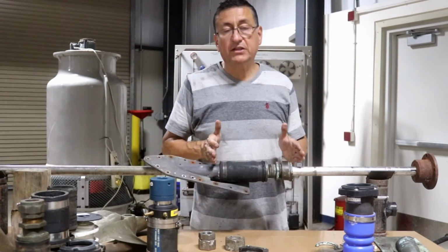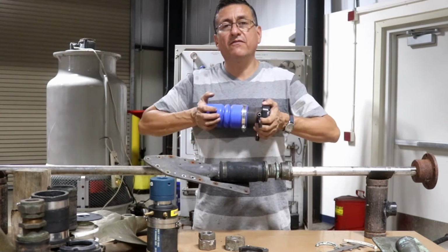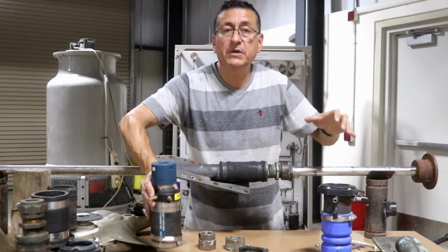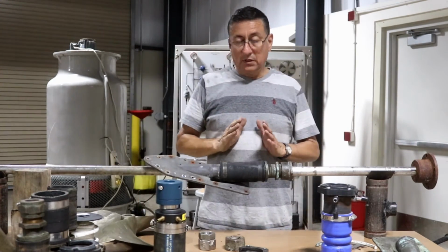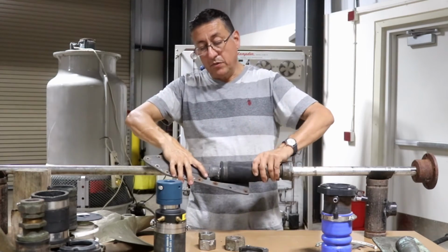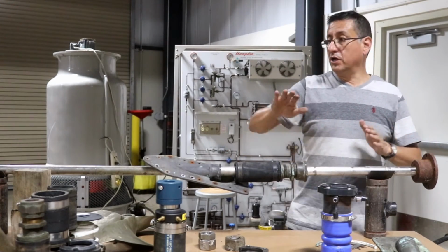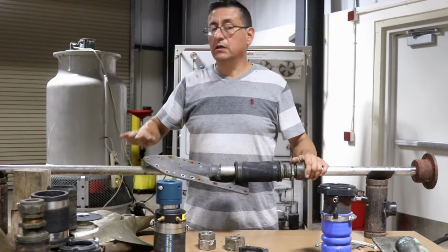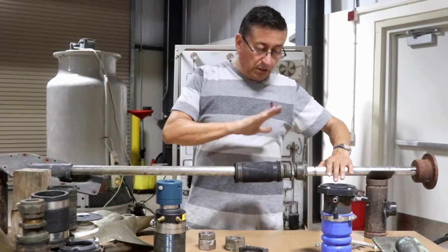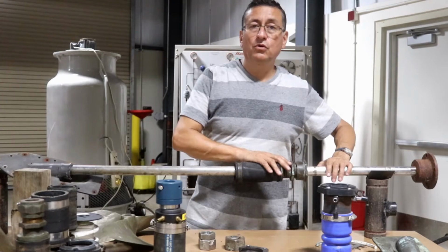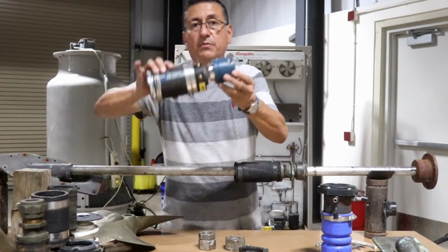Can I replace my traditional mechanical stuffing box for any of those? For the bellows systems or for the PTS system? Yes, you can. It's simple. The idea is to remove the stuffing box. You remove the coupling, and you remove the stuffing box. Or on the other side, you remove the propeller, the strut, the flange, and you introduce the new stuffing box. We are going to install this one, the PTS.